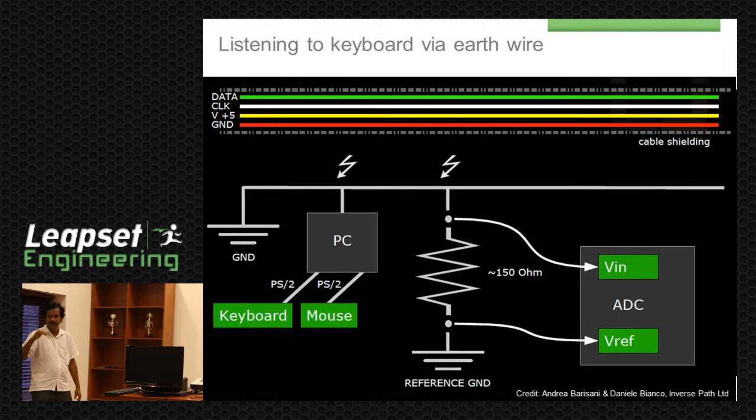It doesn't carry any electricity, compared to the neutral one. It is connected to ground. If there is any leakage, the earth wire conducts that electricity to ground. That's the idea. However, with any electronic equipment, the chassis and these shields are connected, ultimately to the earth wire.